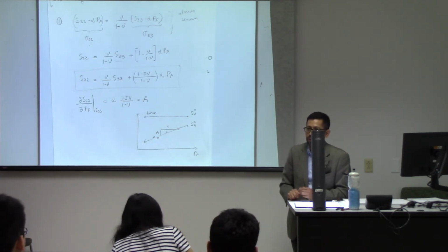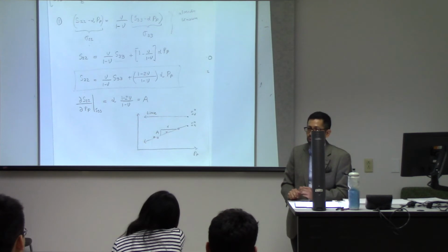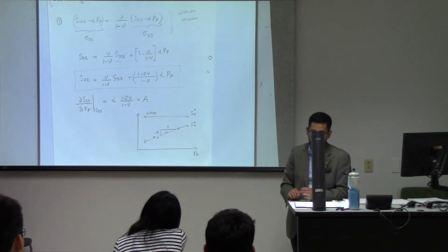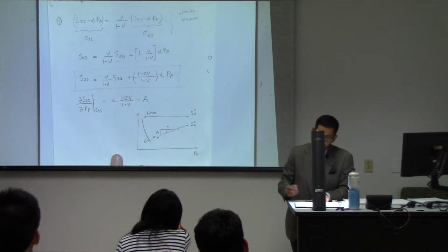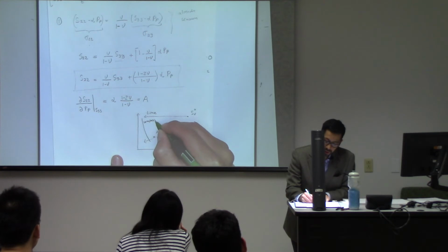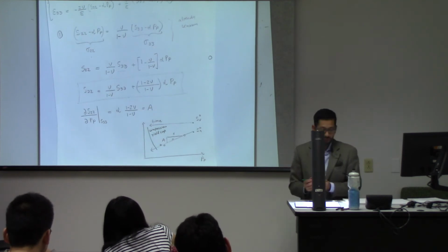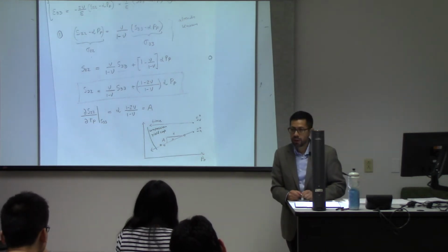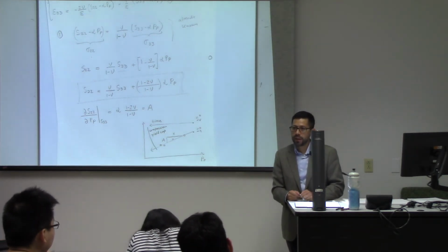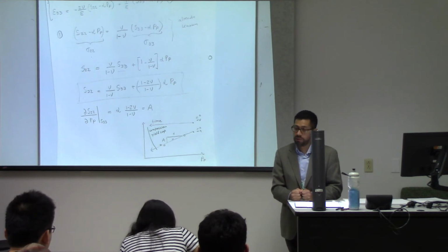You just said the effective stress increases in all directions. The pores may collapse. If you have a rock made out of, for example, a sandstone, you could break the grains. So at some point over here, there is going to be something called a compression yield cap. If, for example, you were dealing with a hydraulic fracture completion, you may create such huge effective stresses that your proppant may crash. And there are cases of that too.